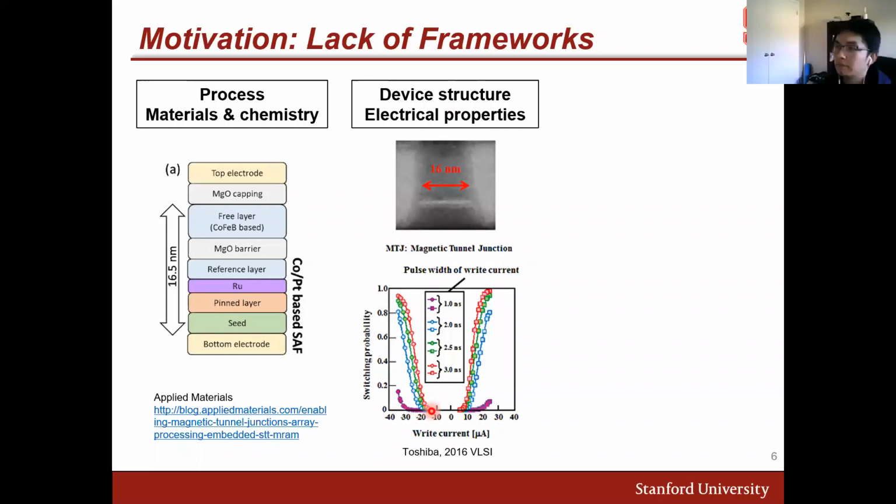So the write pulse, depending on the current magnitude and the pulse width, you can write the bit from 0 to 1 or 1 to 0, and then you can write a lot of times to get a switching probability. Okay, the switching probability is very critical to characterize the device. Okay, with that, we can further build a circuit.